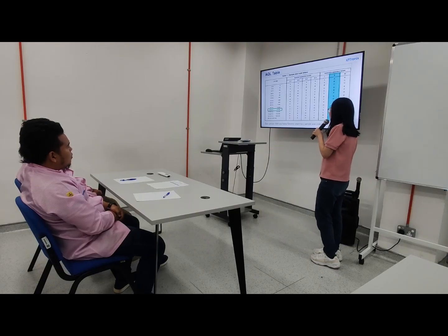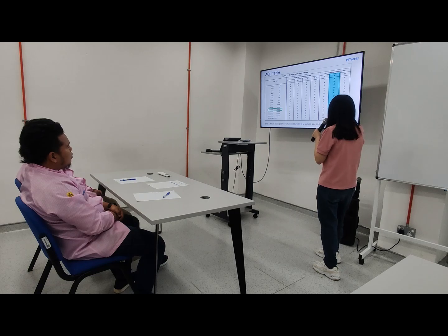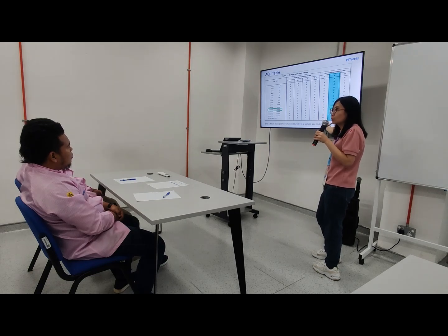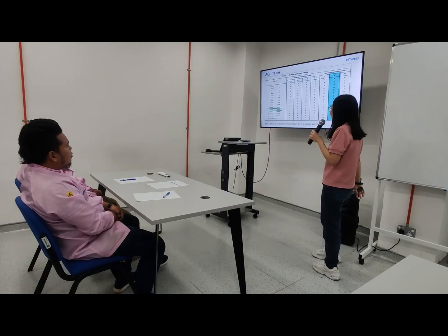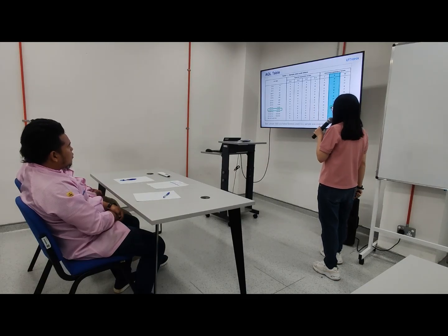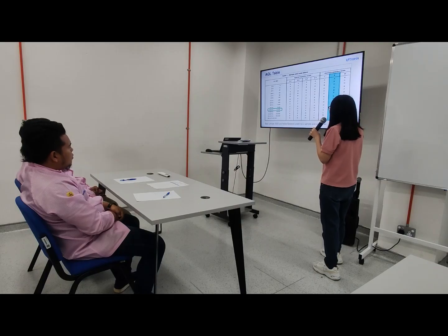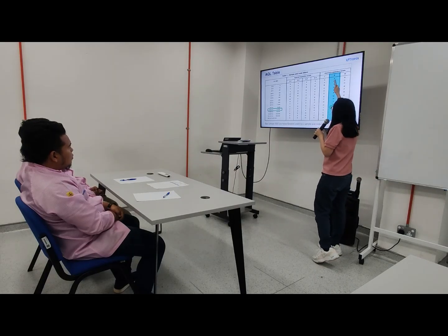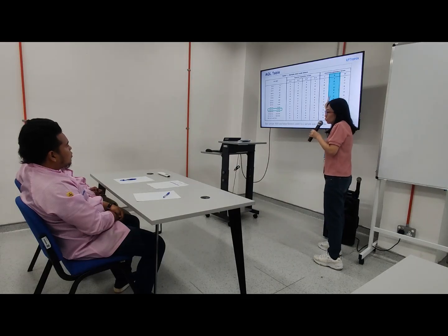Okay, this is the table, the AQL table. Before this table, our SOP also has it, right. For this one, this is the sampling size code letter, and normally for manufacturing we will go for general inspection level 2.